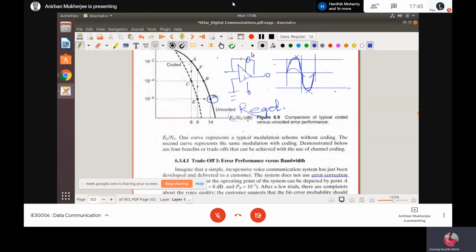So here is your output, say this is your 3.3 volt, this is minus 3.3 volt, and in this output that will always be clipped at 3.2 volt, maybe minus 3.2. And if you have a requirement of a 3.5 volt sinusoid, because in order to get that 14 dB SNR, then what will happen? From this point it will be clipped. Again it will come. This is that 3.2 volt line kind of.